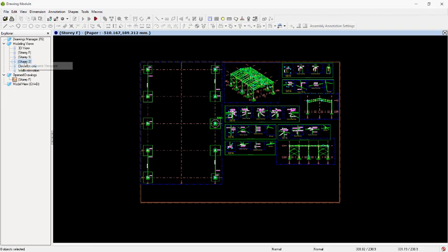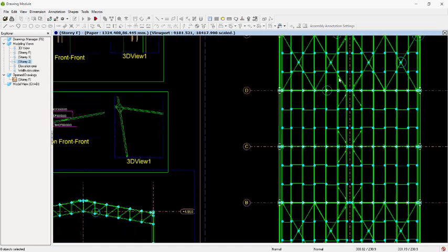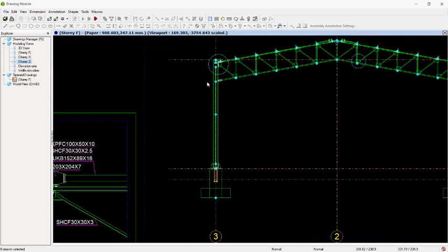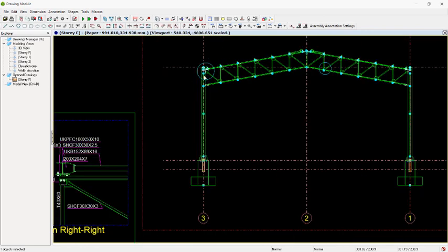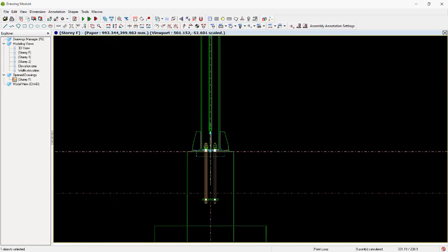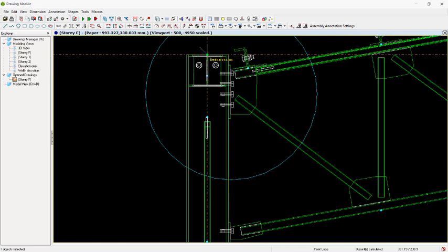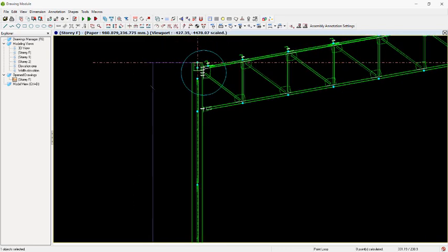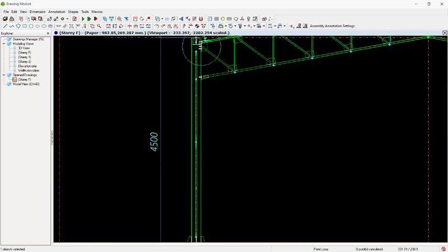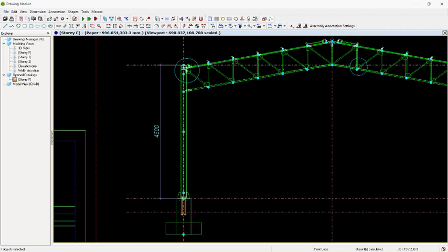So let's check the roof. Create for the roof just like this. Okay, we have the roof here. Okay, so for these elevations, if for instance you want to do dimensioning, you can dimension this successfully. It's very easy. You can use the vertical dimension for the upward distance dimensions. You can pick that point and all the way to this other point of green lines, and then right click to place your dimension. This is 4,500, which is the height of the stanchions.